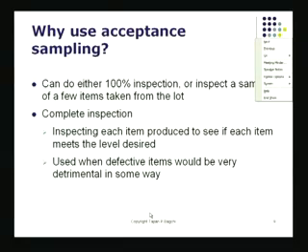So in fact, these are a couple of reasons why one should not try to attempt 100% inspection, except for critical characteristics. Like for example, if there's an electrical component, and there's some chance of it having a critical defect, if it can give a shock to the user, then of course I've got to inspect 100% of these items. So unless the characteristic is critical, I can generally do what we call inspection on a selected basis, based on a sample. That we could do quite easily.